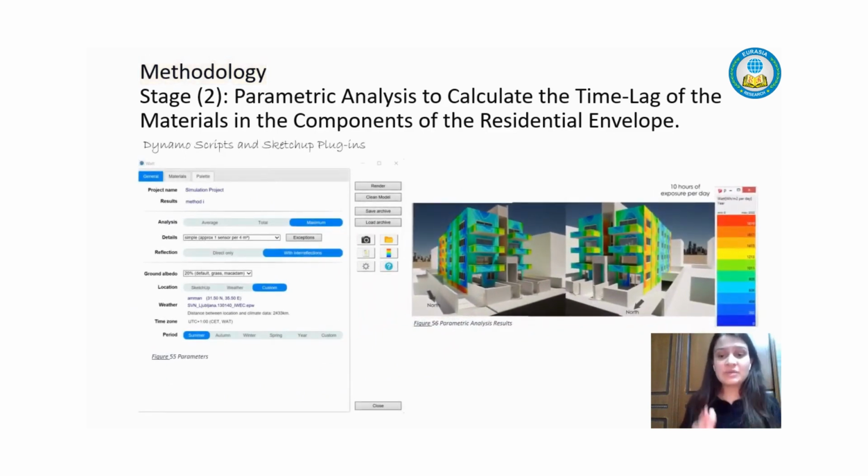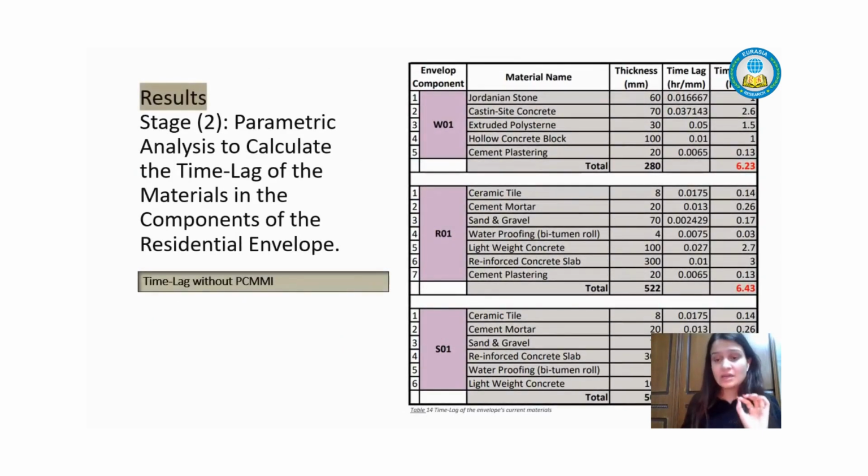So I did this parametric analysis by putting all the variables that I studied throughout this software, knowing the albedo and the reflection, the setbacks, the materials, the surroundings, the vegetation, everything in the climatic area in order to calculate the specific time lag, and by putting one sensor on each 4 millimeters square to understand the time lag and calculate it in a very good way.